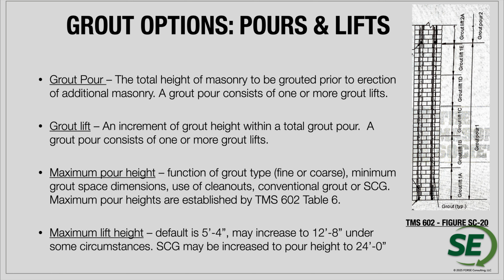What I would try to do is make sure that as a designer, that I do give the contractor some ability to choose the lift heights that they would like to use, grout pour heights that they would like to use as they're building the masonry wall. The code is very clear definitions for the things that they would have to do to meet the different heights for both grout pour lifts.